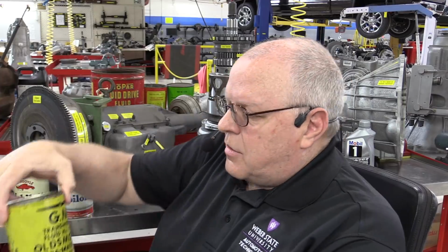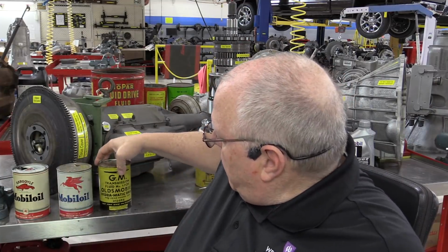But when they went to this transmission fluid here, because of the fluid coupling added to the transmission, they told you to check it every 1,000 miles, change it at the first 5,000 miles that you came to, and then change it again every 10 to 12,000 miles after that, depending on whether or not it was an Oldsmobile or a Cadillac or what model year it was. But about 10,000 miles is all you got out of that old transmission fluid.